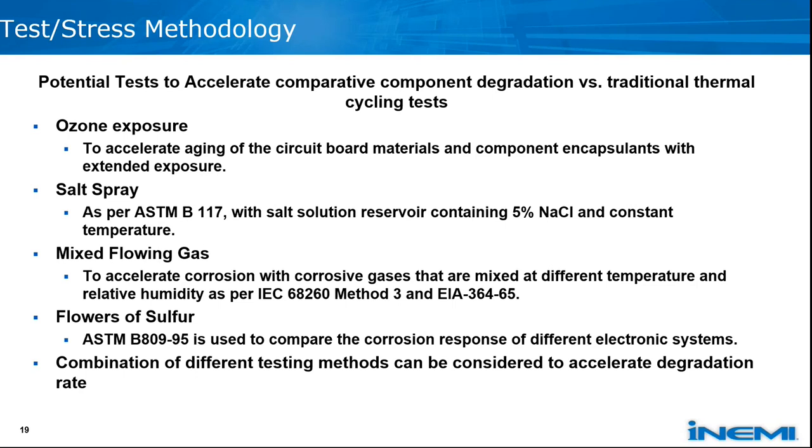Certainly other tests that are commonly used, such as the salt spray, the mixed flowing gas tests, flowers of sulfur, and so on. There may be a combination of these tests that will help us in the evaluation and possibly speed the evaluation, and that's also part of our discussions. Next slide, please.